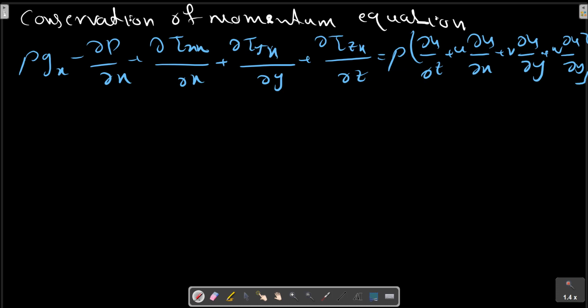Anyway, we continue. This is the differential momentum equation in full glory and is valid for any fluid in any general motion, the particular fluid being characterized by the particular viscous stress term. Note that the last three convective terms on the right-hand side of each component equation are nonlinear, which complicates the general mathematical analysis.